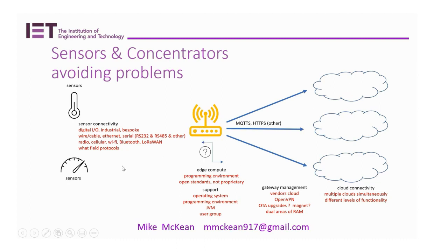These are typically, now I'm talking about more general IoT. I'm not talking specifically about smart homes, and that's important because if you're working in a block of flats and there's equipment there that is managing the elevators, the lifts, or some sort of power environment or building management systems, they might well be using something else such as BACnet or Modbus. And if you don't understand that, you lose credibility. On the positive side, if you do understand it, you might win more business. So what I'm coming to here is this sort of gateway device will often be a small Linux server. It's the size of a large book. It's not huge. And it'll have what's called an edge compute environment, a programming environment.